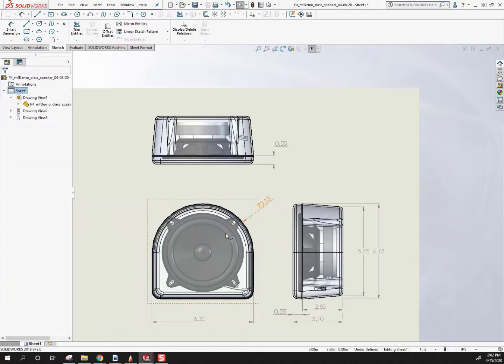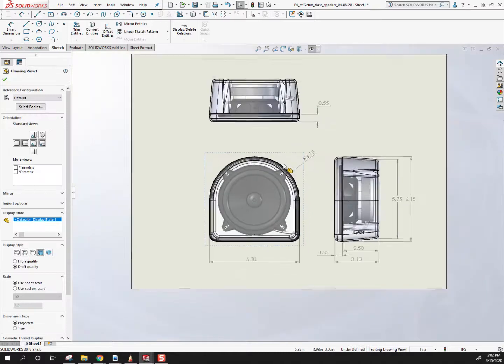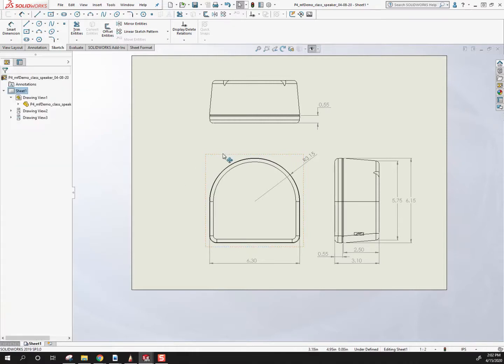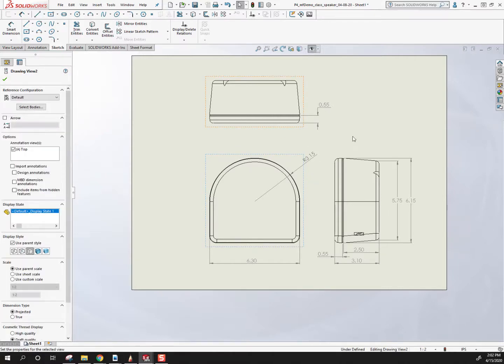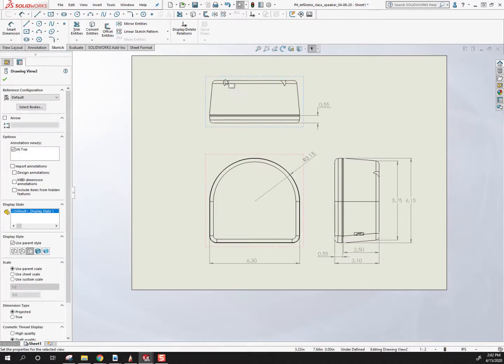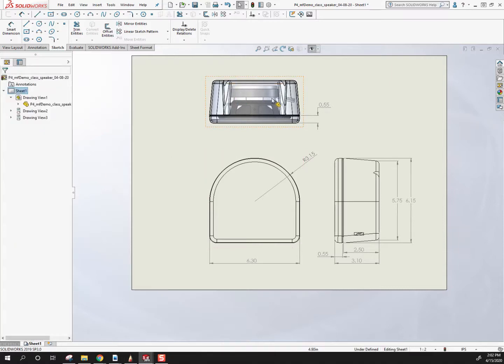Sometimes you may have trouble finding, let me change this view again. Actually, for what it's worth, I forgot to mention this. When I'm changing whether you see line work or shading, I'm changing it on the front view. This is known as the parent, and these are both the children. So whatever this main view does, the children will do. But if I change the view on this top one here, you see it just changes this one.